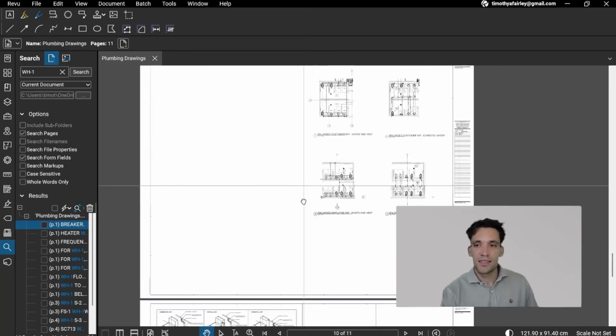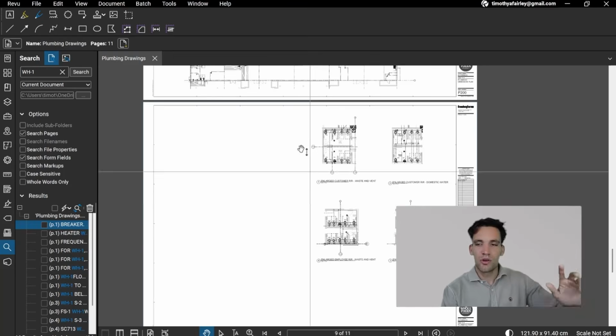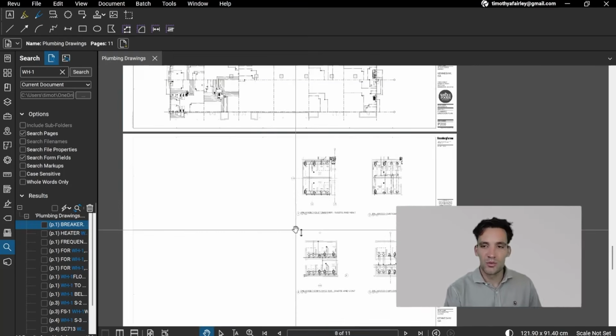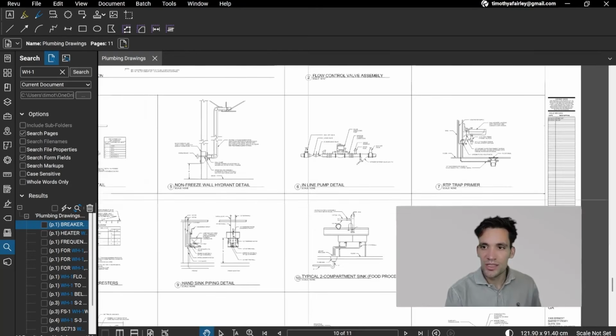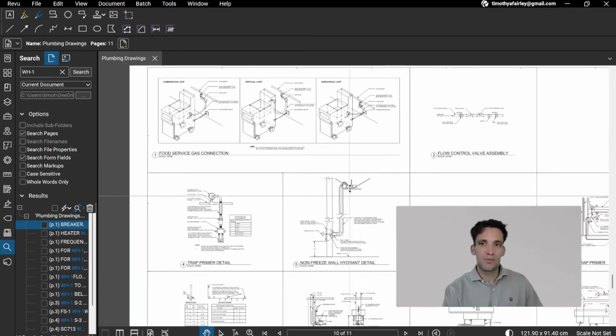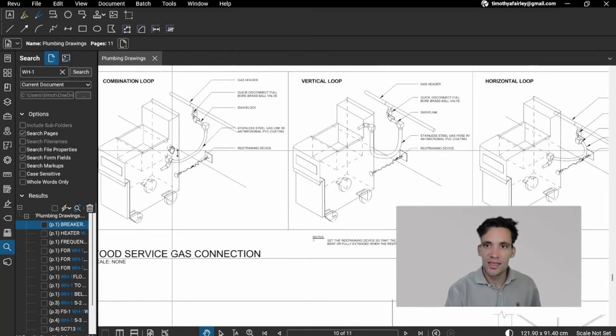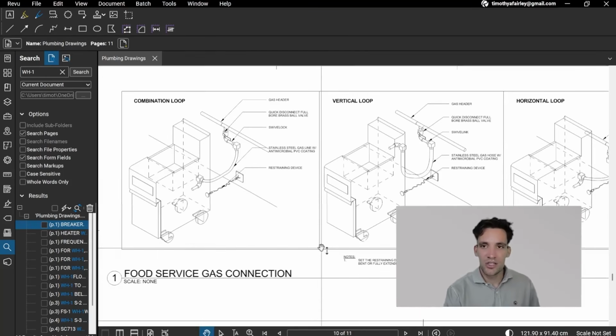The final part of this is, so it's talking about, we've got schedules and general notes. We've got our layout drawings where we can get our lineal meters of pipework. And then at the end, we have section views, which are detailed sort of close-ups or maybe even isometrics, like you can see here, of the exact connection arrangements.